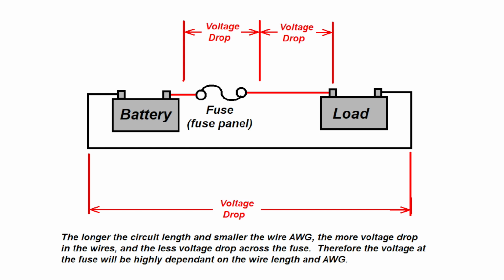The only good thing about this test is that it does show some voltage drop, however inaccurate it may be. This might be sufficient for a go, no-go test when looking for standby currents, so if you have no other method at your disposal, you'll at least be able to obtain some result. Next, let's look at methods of measuring the current through the fuse.